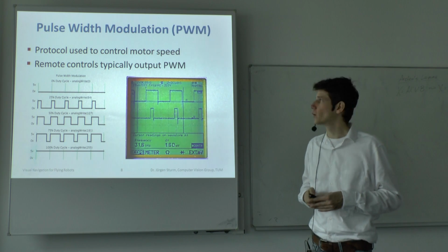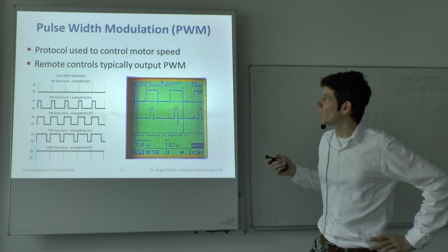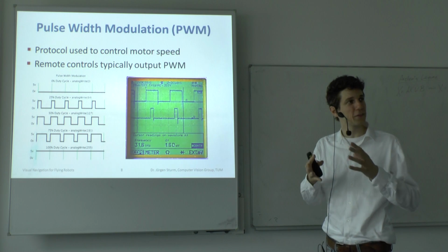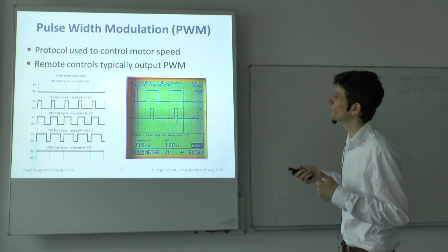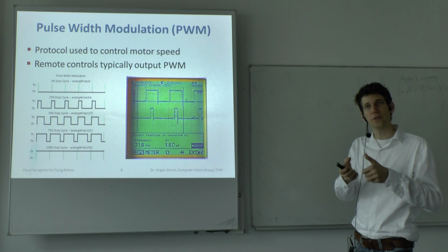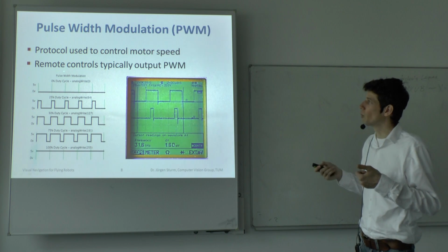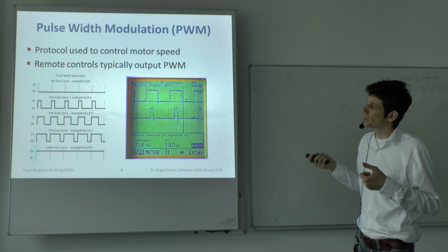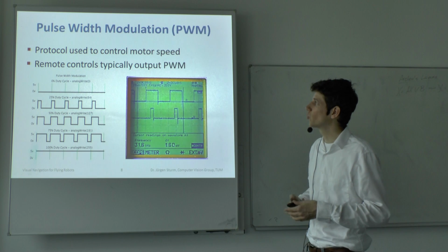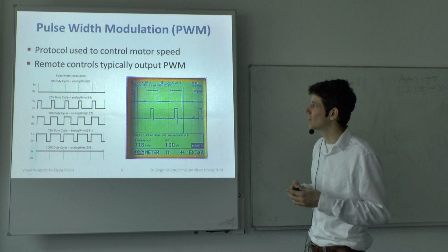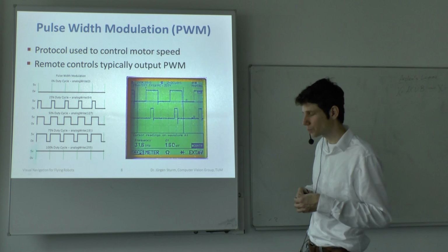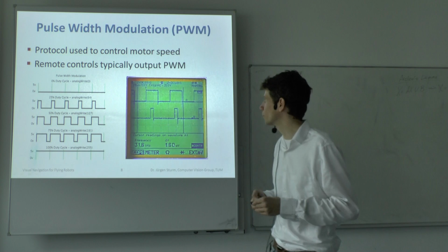More or less. And this is, for example, used by analog remote controls. So when you have a microcopter or a quadrocopter that has an analog remote control, then usually it sends out a signal like this. For every joystick or every axis that you have, the remote control will generate such a signal, and that will be transmitted to the quadrocopter. And then the quadrocopter again has a converter to create an analog signal back from this.